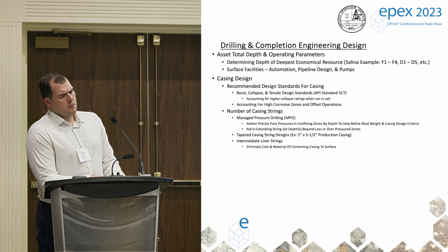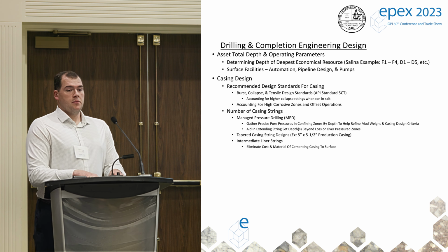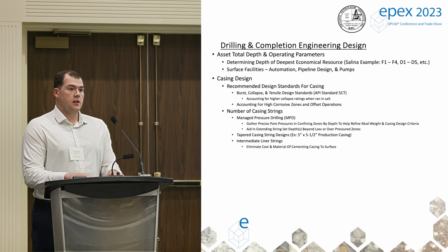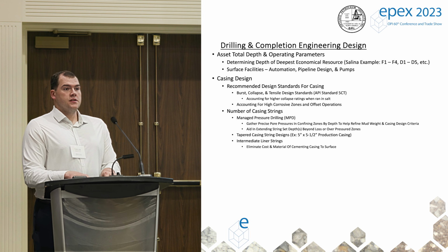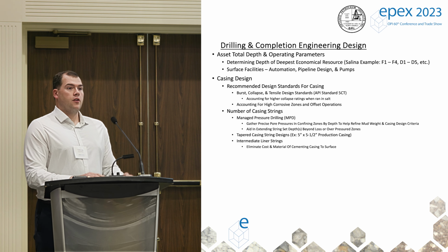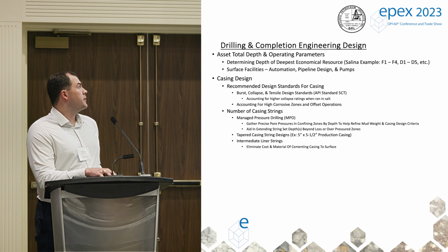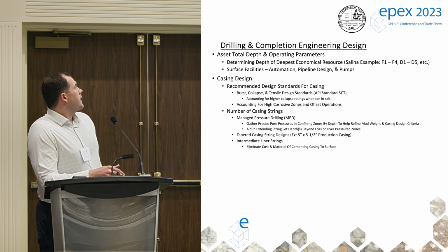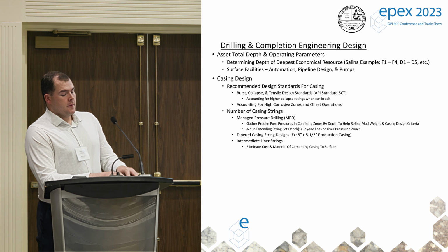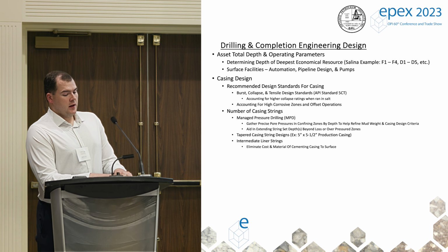And I'm not as sure in the Ontario region if this applies. In West Texas, where we have the Salina Salt development, one thing we have to worry about is shallow injection zones up above, where corrosive environments have been created over years and years of injection with high H2S content.